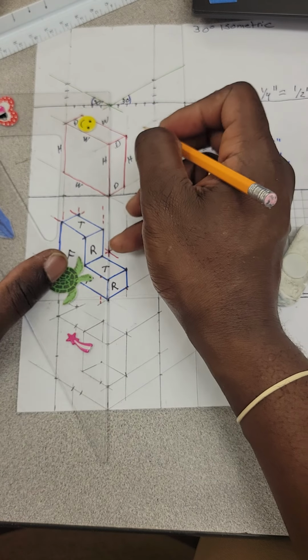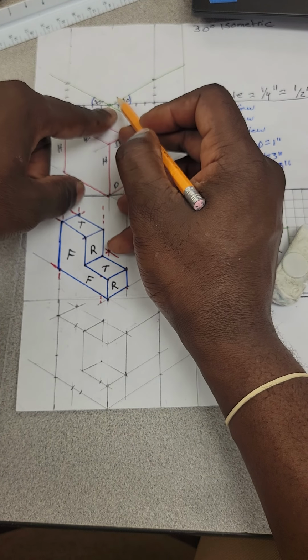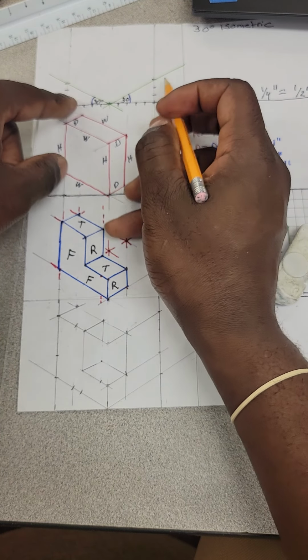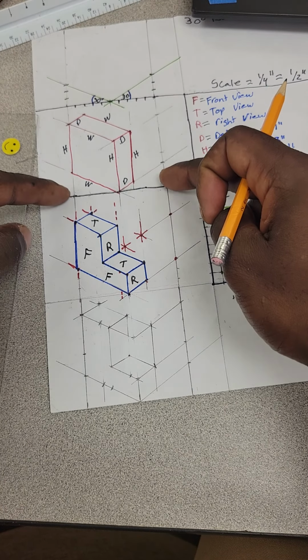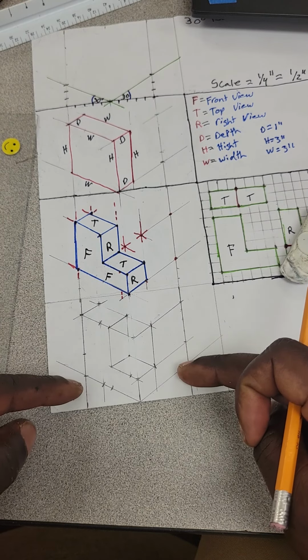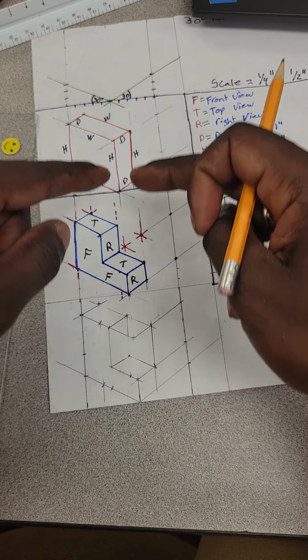It's the same thing in construction. So if you're laying out windows, you find your center point, you do your outs, right? And this is your established one. And every unit is the same. So you just go from center, out, and then lay it down, plumb it down to each window, and you get the same layout throughout everything.